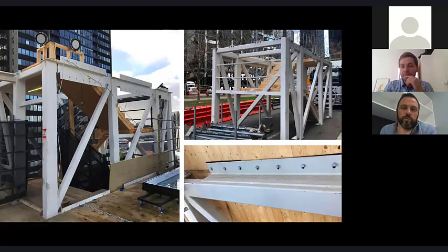Yeah. So what was really interesting on this project was that the steel core was selected for numerous reasons, and it couldn't be timber, but a lot of it was erected stick-wise on site. But with it being next to the mass timber, we saw the elements of prefabrication, and that just led to the steel becoming highly prefabricated on the job as well. And as you can see on the top right-hand corner and on the left, it's a stair that was pre-installed in a factory to the entire level of one of the core steel drop-ins, and we're able to lift that up in its entirety and drop it into place.